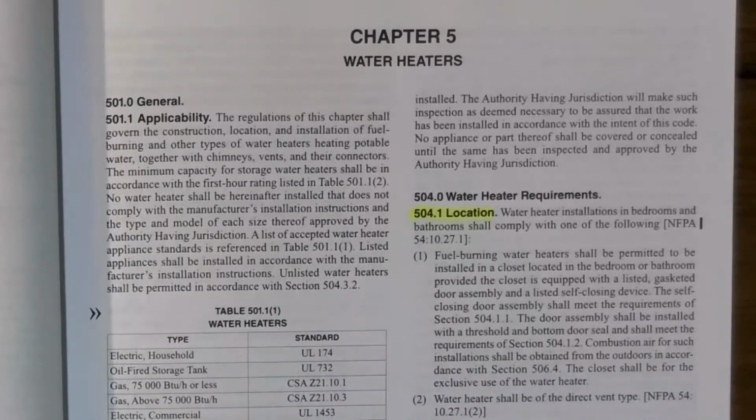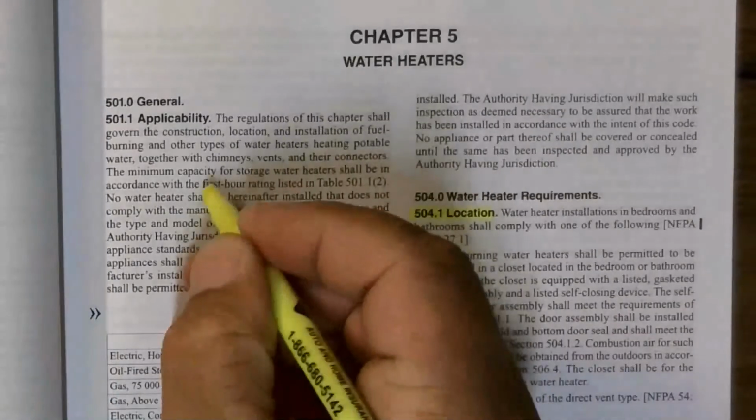So we'll start off with section 501.1, applicability. The regulations of this chapter shall govern the construction, location, and installation of fuel burning and other types of water heaters heating potable water, together with chimneys, vents, and their connectors. The minimum capacity for a storage water heater shall be in accordance with the first hour rating listed in table 501.12. So the first hour rating, which is right here,